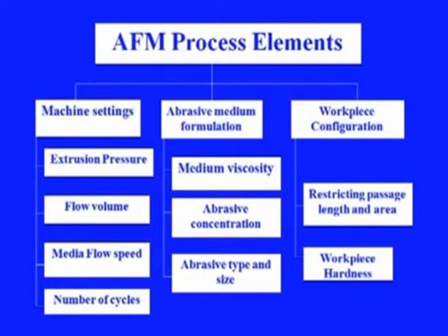On the other hand, abrasive media based parameters include media viscosity, then abrasive concentration in that carrier, and then abrasive type and size in that media. Then the workpiece based parameters include the passage length and area, and then workpiece hardness, etc.